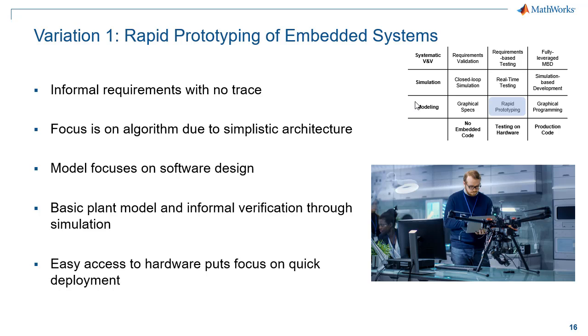Your test and verification in the design phase will involve some tasks, but it won't be to the level of rigor of building up a test management suite inside Simulink Test or anything like that. Instead, you'll do some spot checks, make sure things work properly, and then once you're happy that it works good enough, you'll push it out to hardware and you'll see what happens out in hardware. Okay, so it's all about getting to hardware as quickly as possible, which means skipping some steps. And yes, again, you don't get as much value out of model-based design in this approach, but there's still plenty of value to be had in doing this because of the automated transitions between these different phases of development.